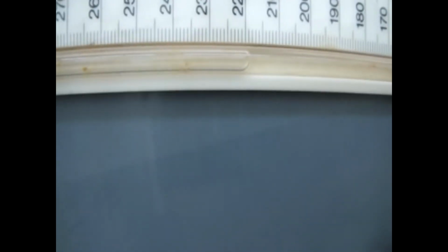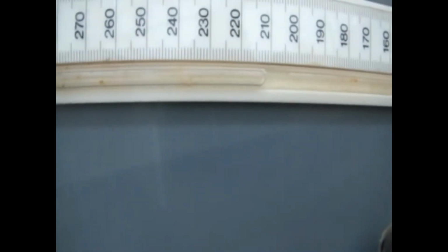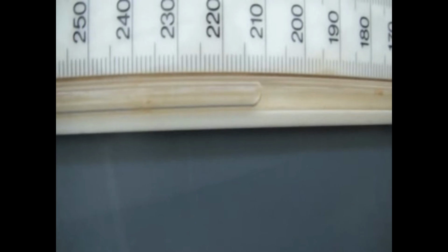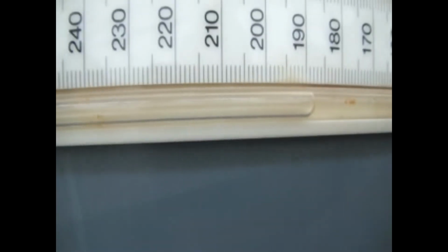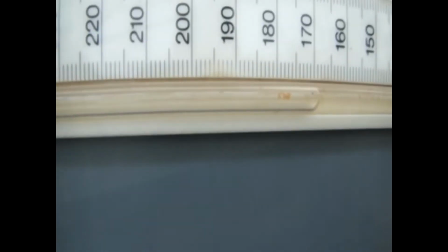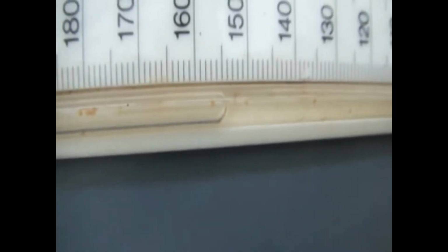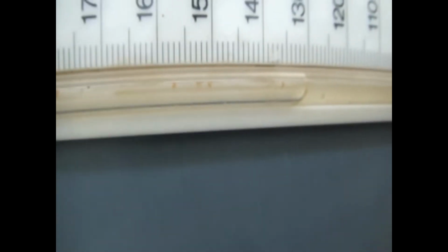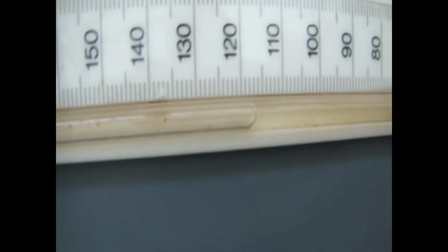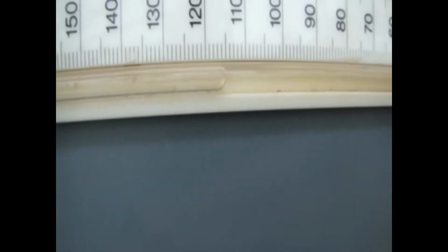The third weight we have removed, it is reaching 213. Now you can see we are removing one by one all these weights slowly, and it gives a reading. So this resembles the removal of soil moisture from the field in the process of evapotranspiration. And if we have characteristics of such kind of soil property, then we can find out the rate of soil moisture removal by the process of evapotranspiration.